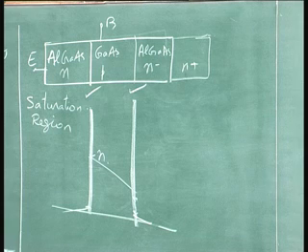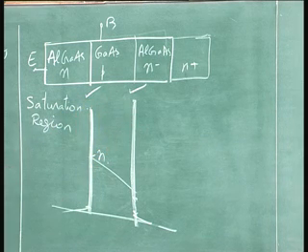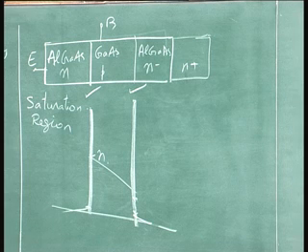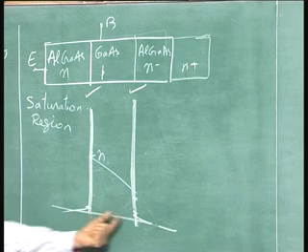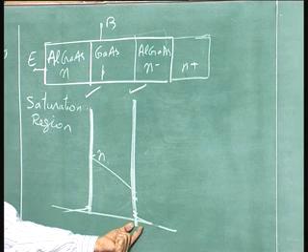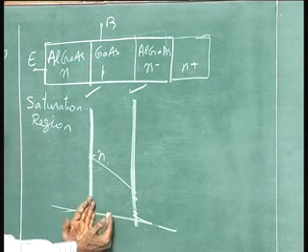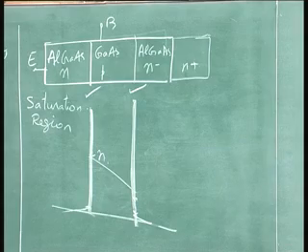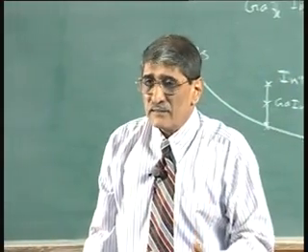So, that is what we mean by saying that even if the transistor goes to saturation, you will not have the stored charge effect. Double heterojunction for switching transistors will be ideal. You do not have to use lifetime control techniques, etc. All that you have to worry about is the charge in that region. No stored charge here, and no stored charge here, because it is wide band gap material. Stored charge here can be minimized by shrinking the base width. So, you are in business for high speed circuits. That is one of the merits of double heterojunction transistors.